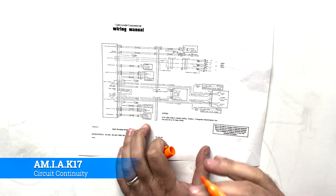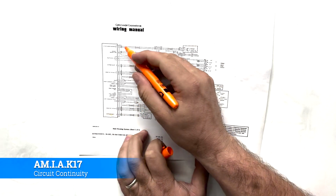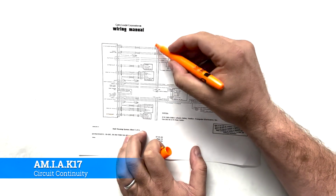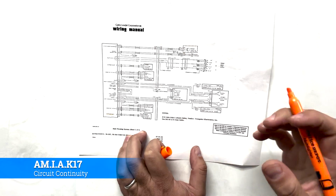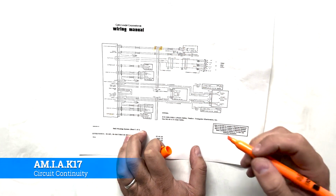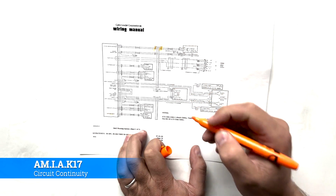And our suspicion, for whatever reason, was that the altitude shift box over here wasn't sending power to the angle of attack indicator. So what could we do? Now, I don't know where P400 is right here, this guy, but let's just say it's in an inaccessible spot. So we have this twisted pair that's indicated by this little infinity looking symbol there that is pinned out on E and F on this side and W and B on the other side.